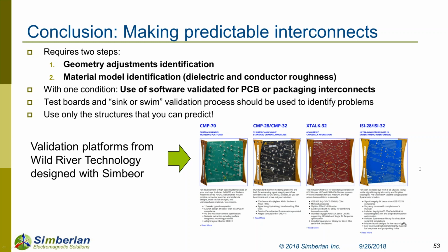For the manufacturer of the foil, for the PCB manufacturer, we have nothing. Again, it leaves us in complete uncertainty. If the foil is manufactured rough on both sides and we got parameters for those roughness, then it may be usable for models. But in reality, one side is roughened by the manufacturer of the foil, another by the PCB manufacturer. By the way, we can stay and answer questions as long as it takes. We are not limited and restricted on timing as in other webinars. We are not going to suddenly leave in 1 minute.